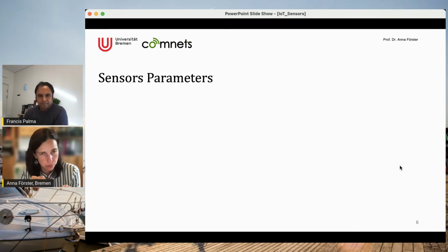A hardware interrupt means that this interrupt is coming from one of the hardware components, but it can come also from a software component. For example, when I was giving you this explanation of the split event and the active sensors, I cannot simply read the sensor value immediately because the measurement has to be started and then measured. So instead I say start the measurement, and then I leave it to do it.